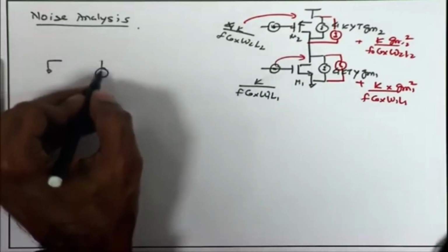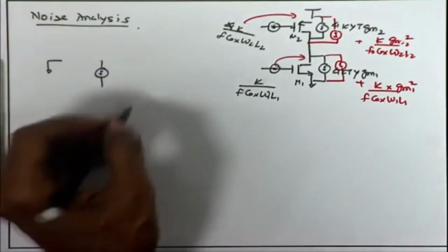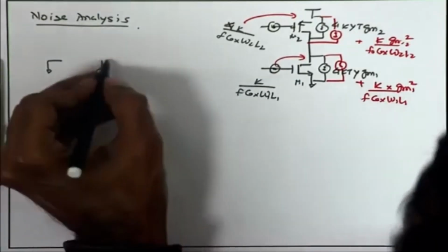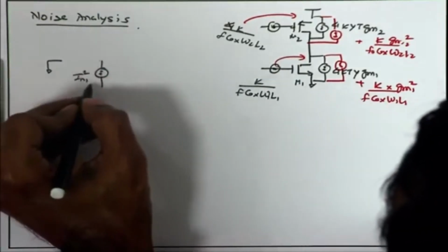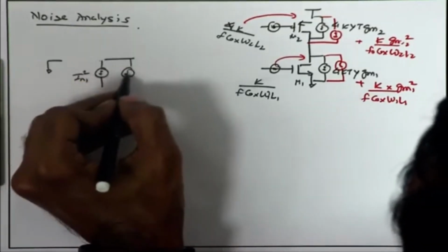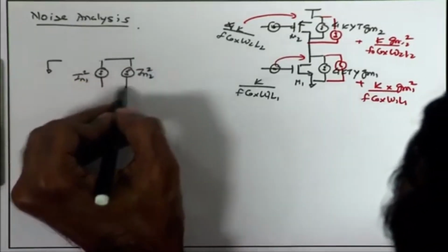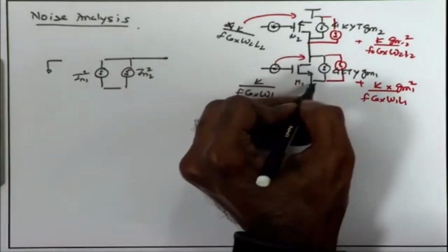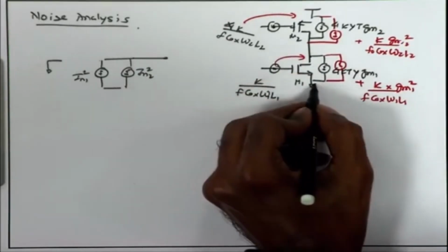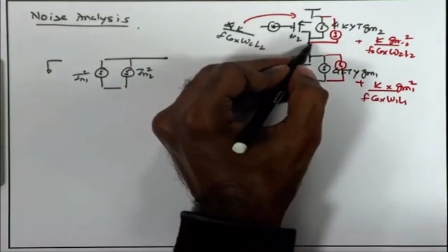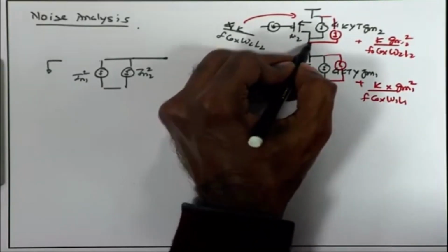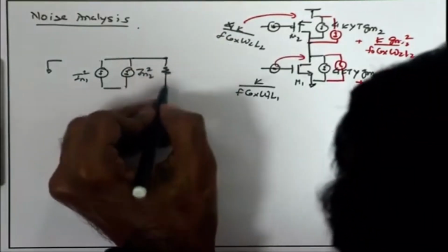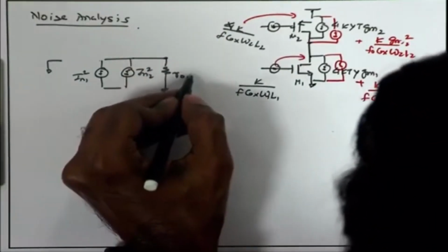and here I have captured the total noise current because of M1 by multiplying the input source by GM square. So, I can call it IN1 square, and likewise I have also captured IN2 square, and we know from drain to source we are going to have the RO of M1 between drain and AC ground. Likewise, we are going to have RO of M2, that is RO2, between drain and once again AC ground, which is VDD. So, once again you have RO1 parallel RO2,